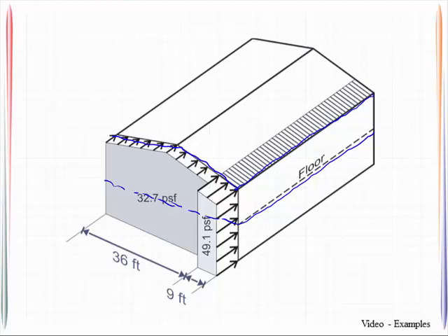We will take a line and we'll draw it halfway between the location of the floor and the location of the roof. We'll come over here with a horizontal line. Maybe if you want to view it this way, it's halfway there. And so this dimension from that point to that point is half of 10 feet, which is 5.